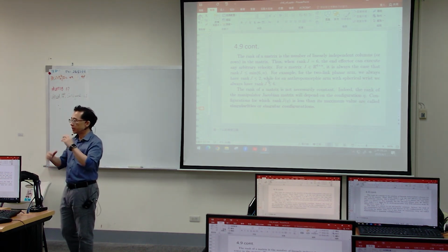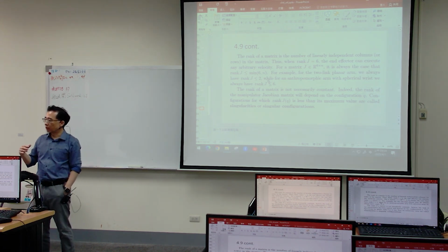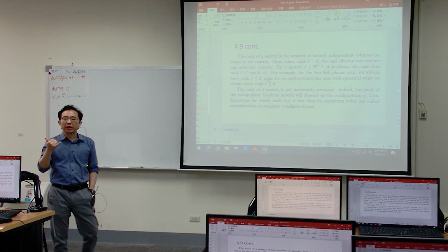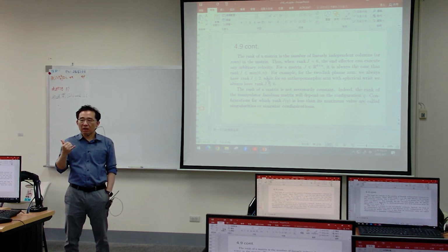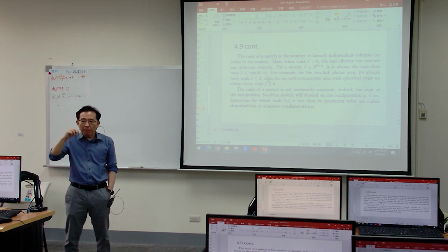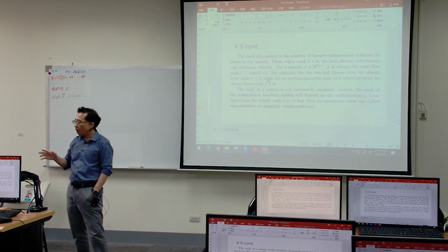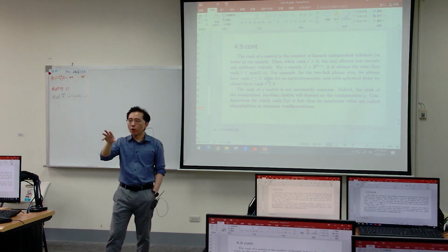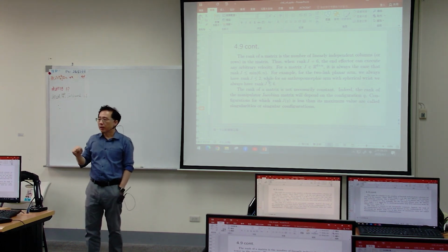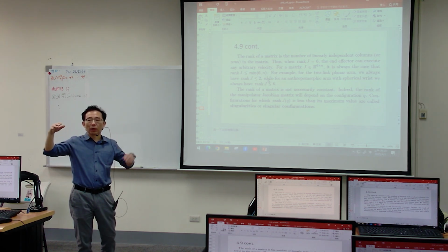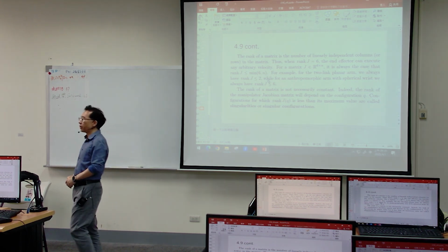That is, in some case, you don't have exactly the answer you need. For example, if you have a 6 degree of freedom robot, initially you have 6 motors or actuators to input whatever you need to move the robot to somewhere you want. However, some joint did not move as you expect, because the input and the outcome are not equal. Then that is singularity.